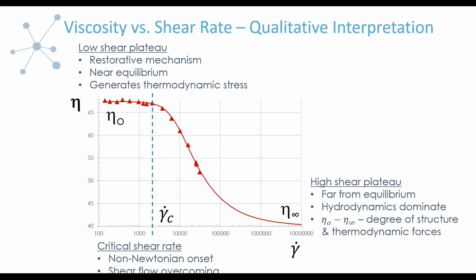We're not talking about the thermodynamic interactions where you have possible contact. What we're talking about is the influence of the fluid environment on one object due to the motion of the other. So you're interacting through this viscous fluid. So you can never eliminate that, no matter how high in shear rate you get, because you're forever having these molecules in a fluid. So that's the transition from the thermodynamically dominated down here in the low shear region to the hydrodynamically dominated in the high shear region.